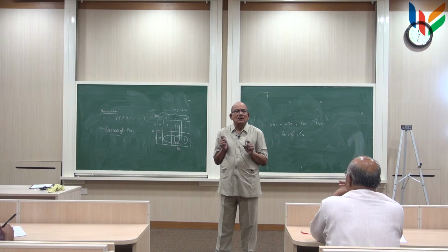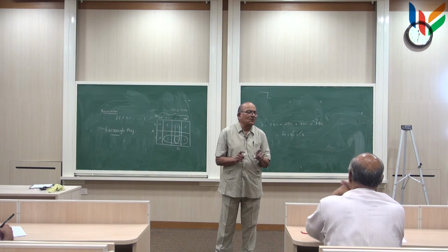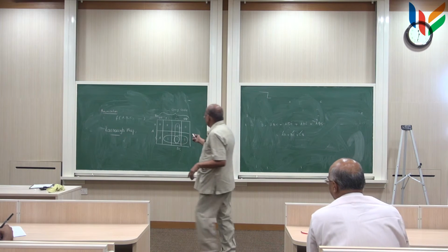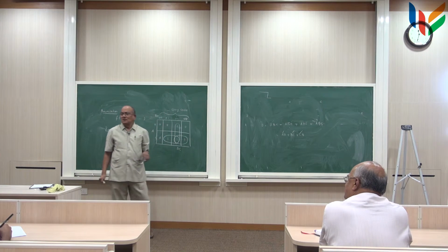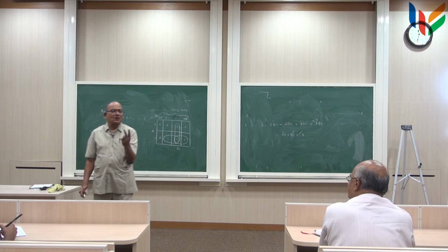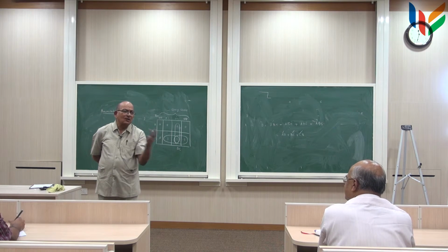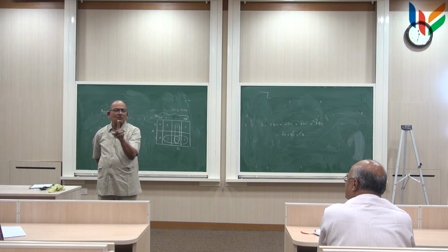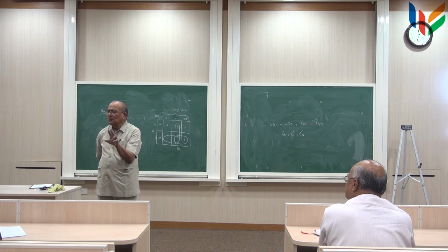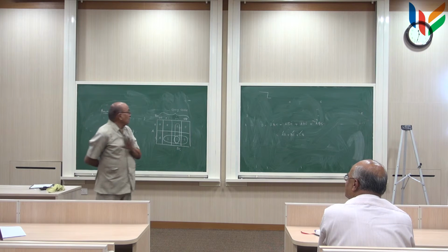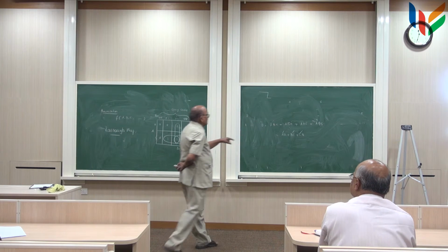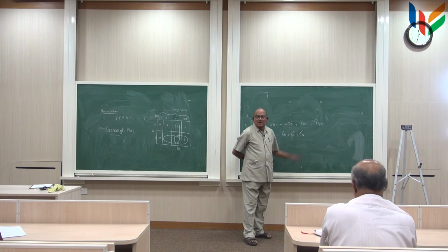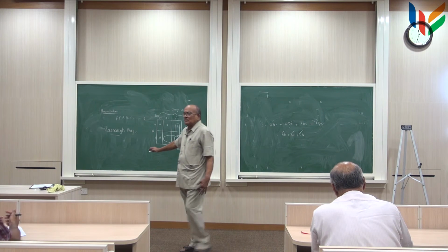So, you look at neighbors which are 1s. In this case, the neighborhood is either a vertical line here or a horizontal line here. Take two of them which are neighbors, which are 1s, and look at the corresponding ones in which there will be one Boolean variable having both 0 and 1 values. So, that is an irrelevant variable. So, the remaining is what is left. Look up and exhaust all possibilities in this, and automatically the resulting expression is the minimum expression, provided you have done it carefully. Okay?